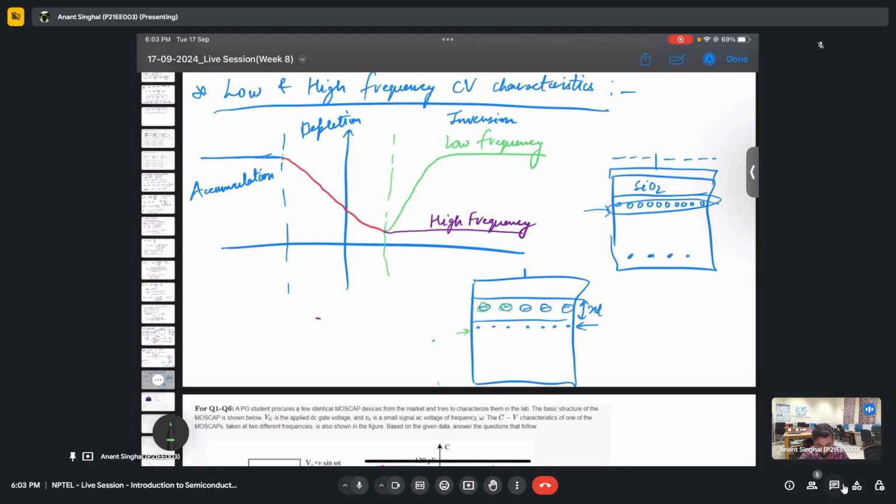There is a difference, sir. They were exposed because of some electrons occupying some hole spaces, right? Yes, exactly. So now when electrons are generated because of thermal generation, would that still revert back to the non-ionized state, thus losing the depletion layer? Yes, yes. So that is what is happening now. When we are going from depletion to inversion, we are losing this, and that is why this capacitance is increasing, right?